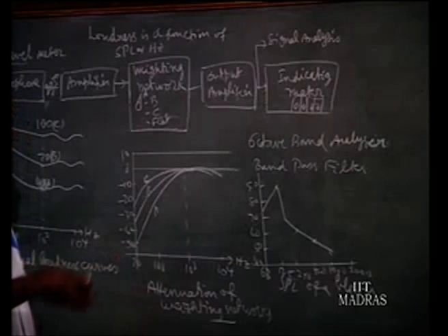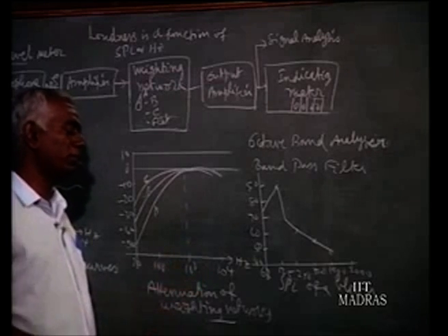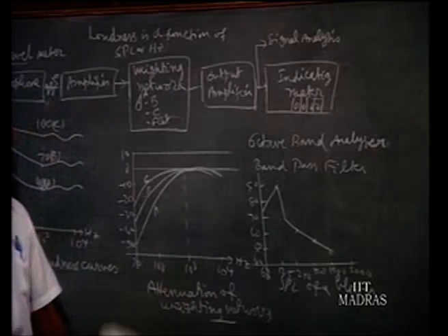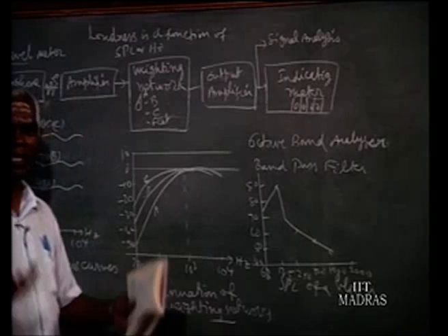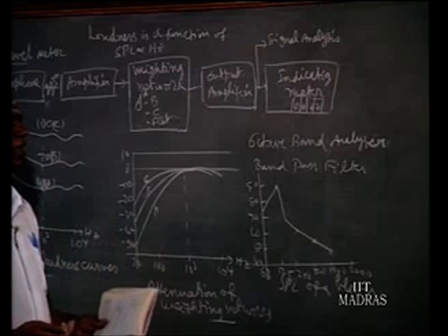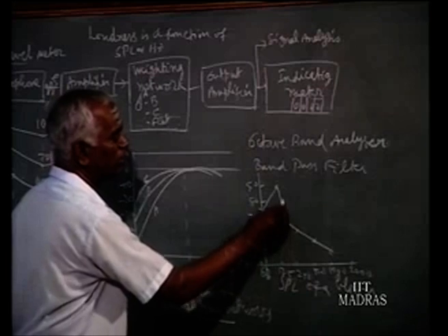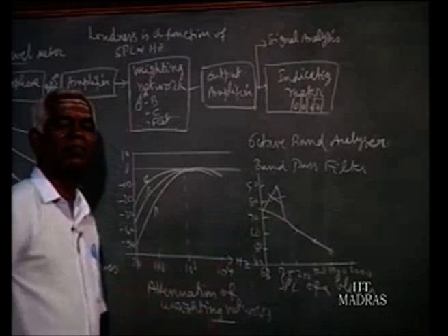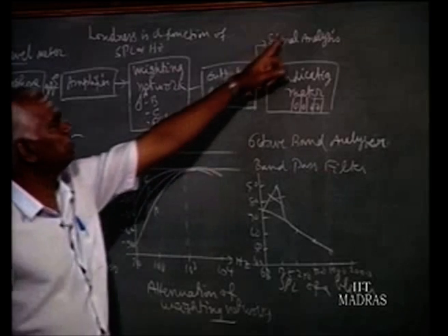Then we find one of the two gear machine gears, and if they are metallic, we can change it to, say, one plastic gear. A gear machine with one plastic gear and one metallic gear will make very less noise. Then after making that, measure again, and you will find this peak will go away. Like that we effect improvement in reducing noise in many equipment. So, for that purpose we can analyze this signal also.